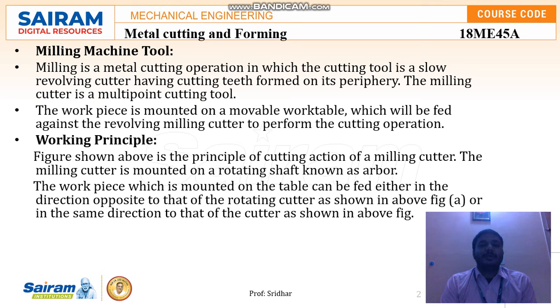Based on the type of workpiece material, we can form the gear teeth. Similarly, if I use a slot cutter, the slot produced may be an end slot, a T slot, or an L slot. Depending upon the type of slot, we use different cutting tools, so different machining processes can be done in milling machines.